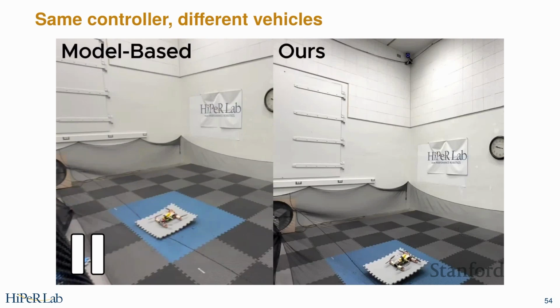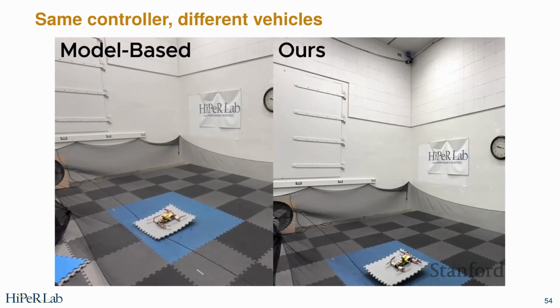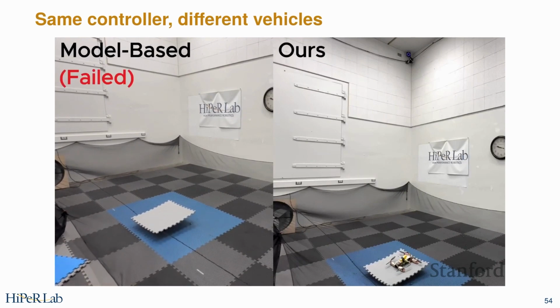So it's starting like, it has no information. We messed with the system. What we did is we took the front propeller and we induced a fault by just reducing its effectiveness by 20%. We do this in software. So whatever command the controller gives, we just reduce that by 20%. And on the left, again, the lab's standard controller fails.